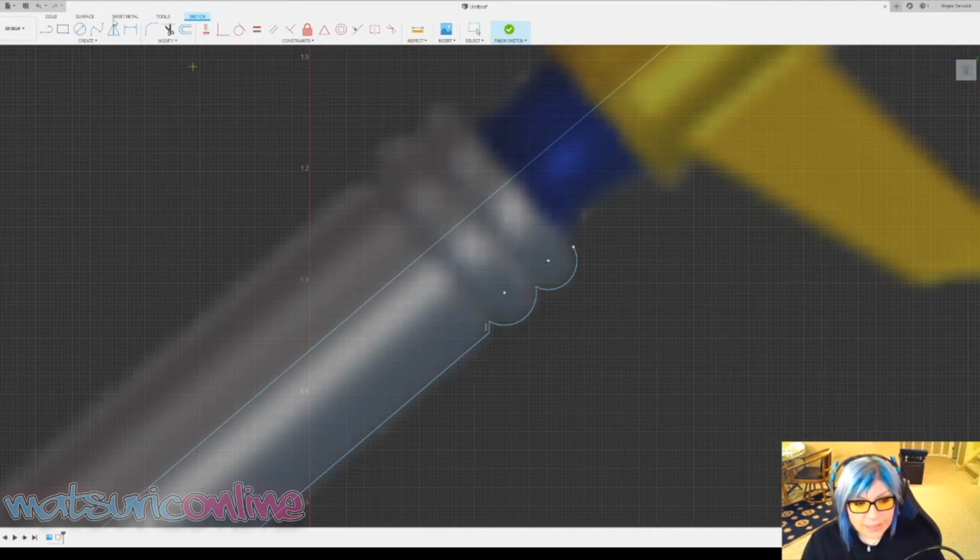The next thing that you may want to do, if you want these arcs to actually look the same, one of my suggestions is you press the D button. The D button has a function called sketch dimensioning. Sketch dimensioning makes it a lot easier for you to scale your part. Or if you are just not happy with how far something is, it helps you keep distances in mind when you're doing it.